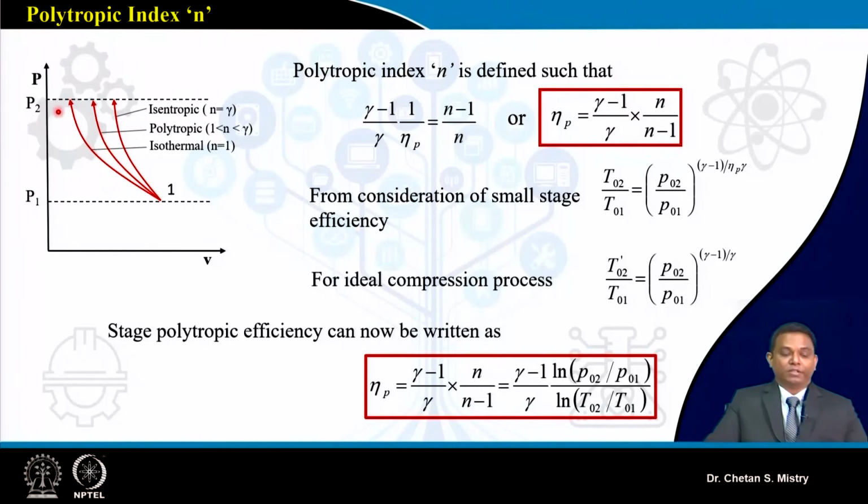From our fundamentals, the work required for compression using the isothermal process is low, and that's why many industrial applications go with the isothermal process. Now the question is, how do we do this compression process isothermally? The reciprocating compressor works nearly in a quasi-static way, and we can assume that as an isothermal process.